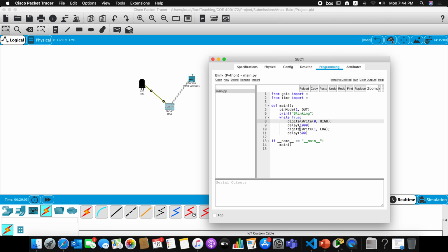In fact, if you know programming, this is nothing but an infinite loop. It comes here and it keeps doing this all over, forever. So I'm going to set the pin of 0 to out, meaning it's going to be an output port, and do this forever. Just set it to high, meaning 1 in binary, which means on, and then turn it again to off. So set port 0 to high, set it to off, and between that we have just some delay, just to delay the operation, so we can at least see how it changes.